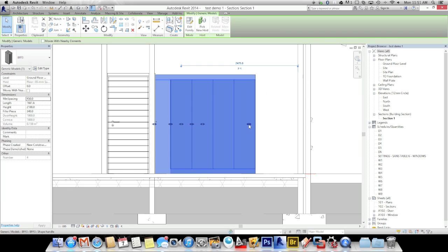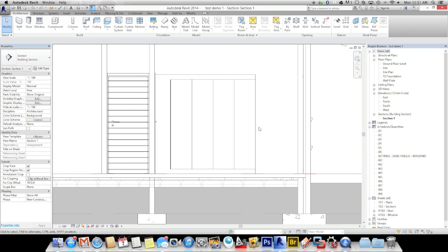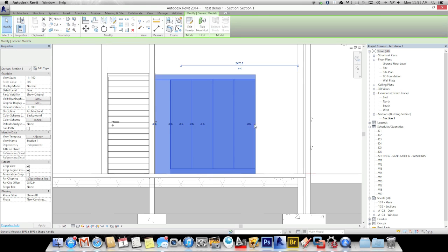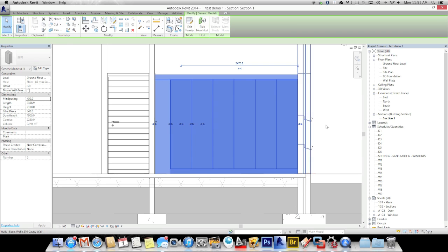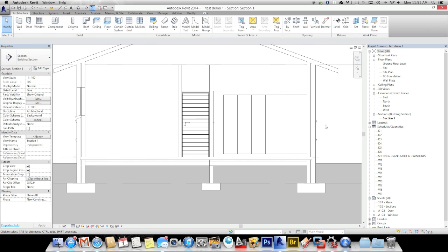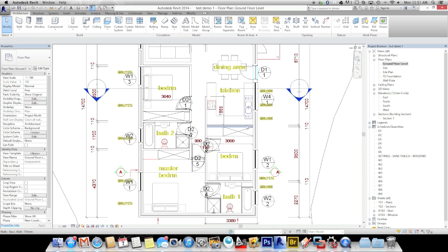Every 450 it will add or subtract a kitchen cupboard module for you. Let me just undo that and pull that back to there. A bit more, to there. So that's cupboards. So go ahead, finish off the floor plan, adding sanitary and built-in cupboards.